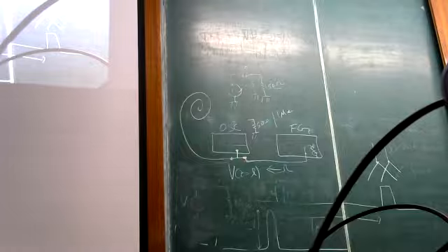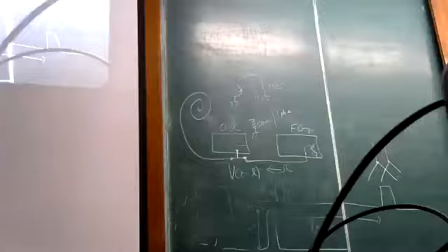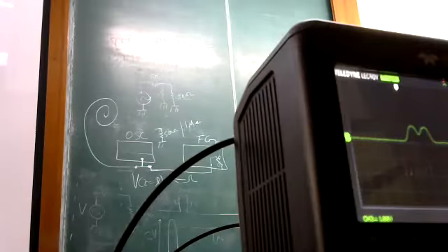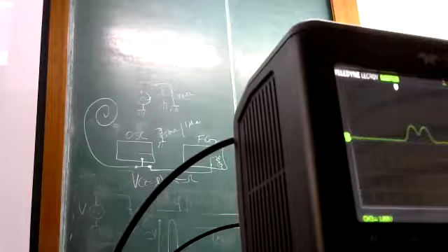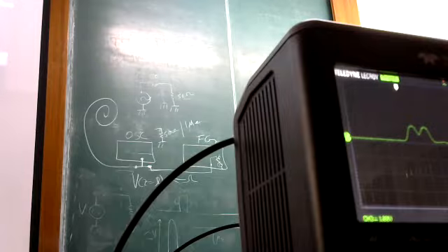It was already half. So we have 2/3 of the current value, because this is already V by 2. What we just saw, these amplitudes are already V by 2, where V is the source voltage. And now we said that the new pulse is going to be 1/3 of the original value. So it's going to be 2/3 of this value.